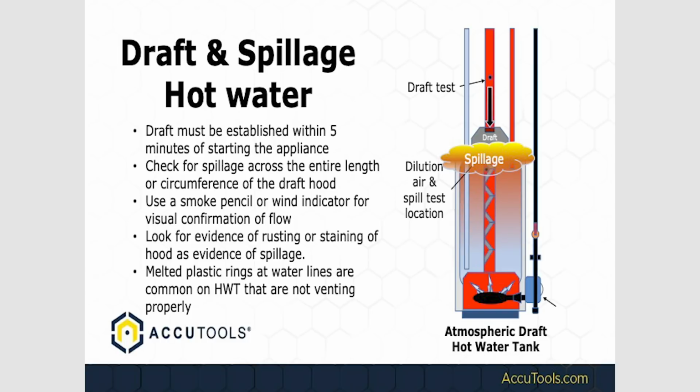Draft on a hot water tank, again, must be established within 5 minutes of starting. So many guys walk in, they test the furnace. I have seen more hot water tanks making large amounts of CO than I ever have furnaces. Hot water tanks are a huge potential source of CO. Anybody know why? Who puts in hot water tanks? Homeowners do, yeah, and that's the problem, right?